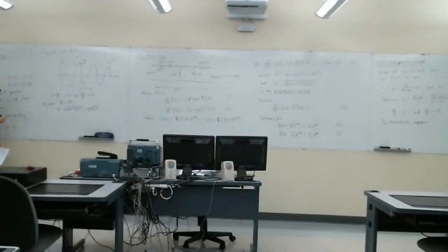So again, this implies that alpha is 0, and that goes along with no resistivity, no conductance. Okay, alpha is 0, there's no attenuation in this line with this approximation. And in real life, we know there is some. I talked about, over 100 meters, it's got 16 ohms of resistance, but it's a pretty good approximation.